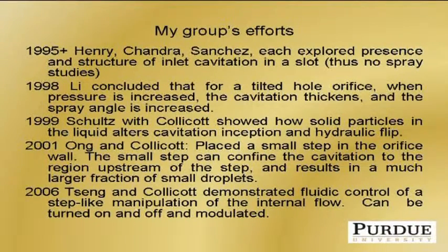In '98 then, Hyun Lee, who's now with Pratt & Whitney in East Hartford, Connecticut, concluded that for a tilted hole orifice, such as in a Cummins diesel injector, when the pressure is increased, the cavitation thickens and spray angle is increased. I'll show you some pictures from that. That was a true scale, true pressure visualization inside a diesel hole, so 200 micron diameter, 2,000 atmosphere flow visualization inside the hole.